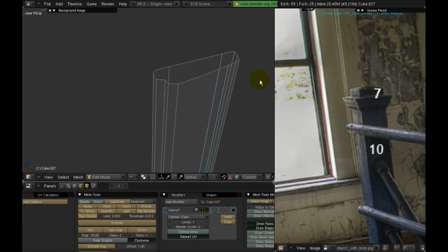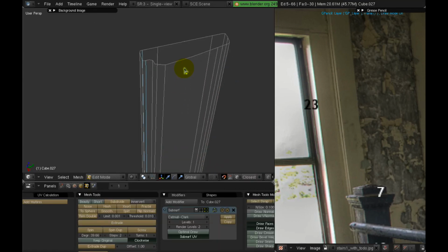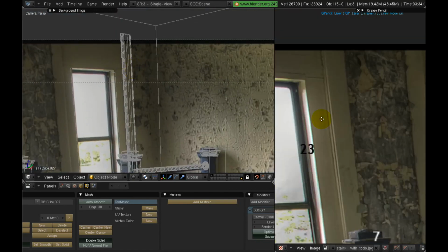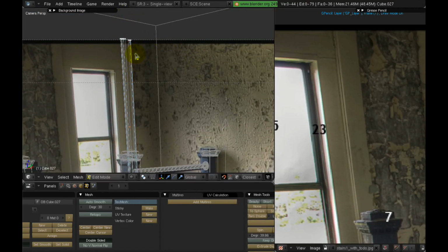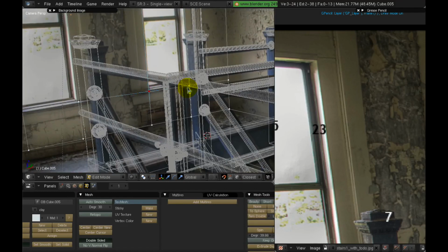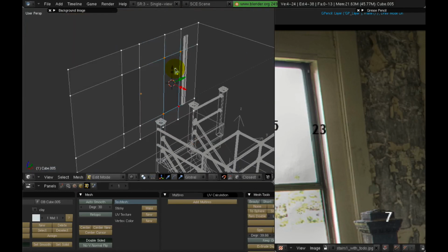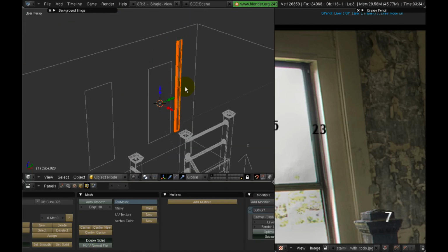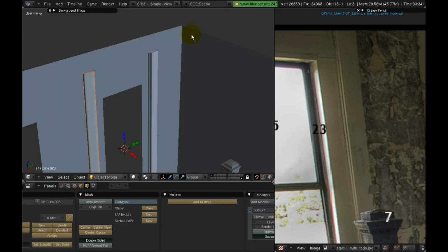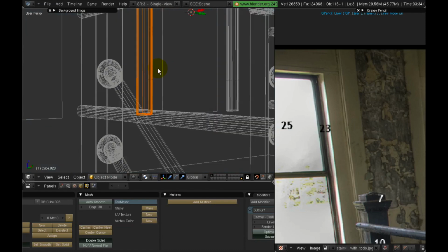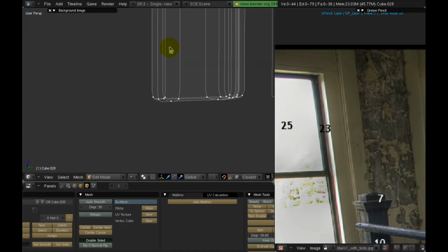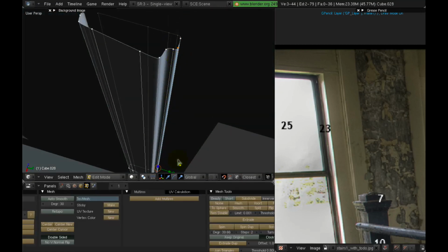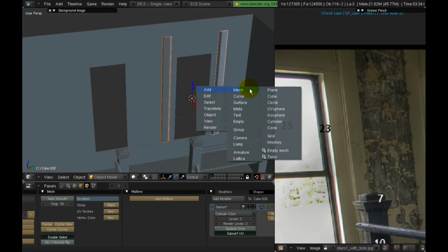And we've got a Subsurf Modifier applied, and we're adjusting the controlling loops to control how we want the actual turn of the surface to go, how sharp or smooth we want it. And I'm selecting the vertices of the opening and snapping the cursor to that, and also centering the object to that, its origin, and then scaling along the x-axis a duplication of the first part, and also have the object data linked using Control L.